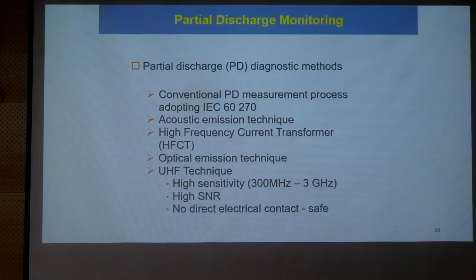So these are very high frequency discharges. In that way we can develop ultra high frequency techniques and sensors to pick up these signals. If we design it appropriately for the particular bandwidth, we will get a good signal-to-noise ratio.